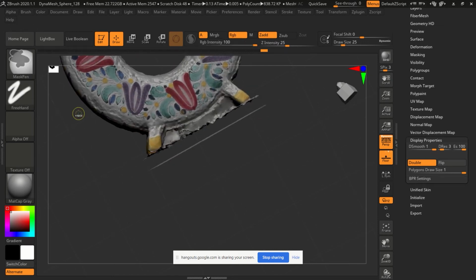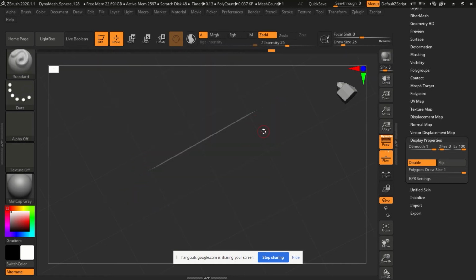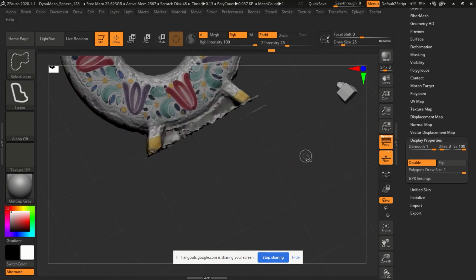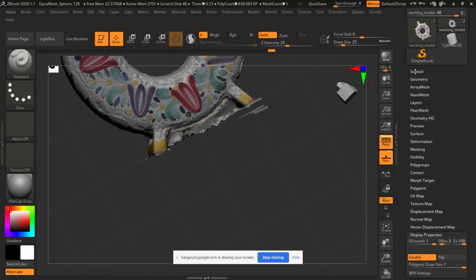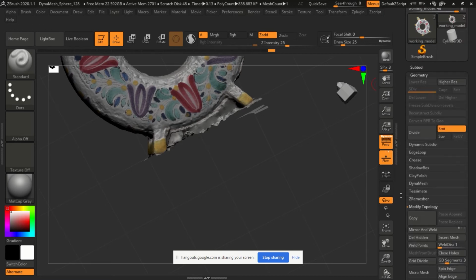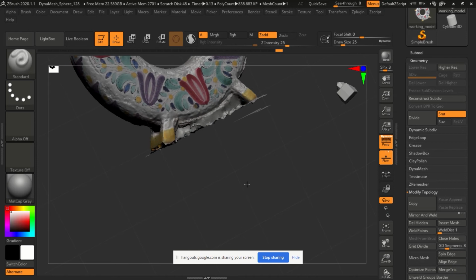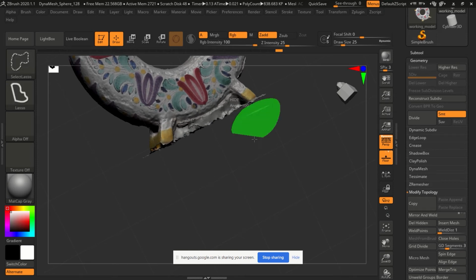by, again, Control Shift. I'm going to change the lasso tool because I'm on an angle. And then I'm going to select that and invert, right? That's selected. And then go back up to geometry and delete hidden. All right, I'm going to quickly grab this one as well.